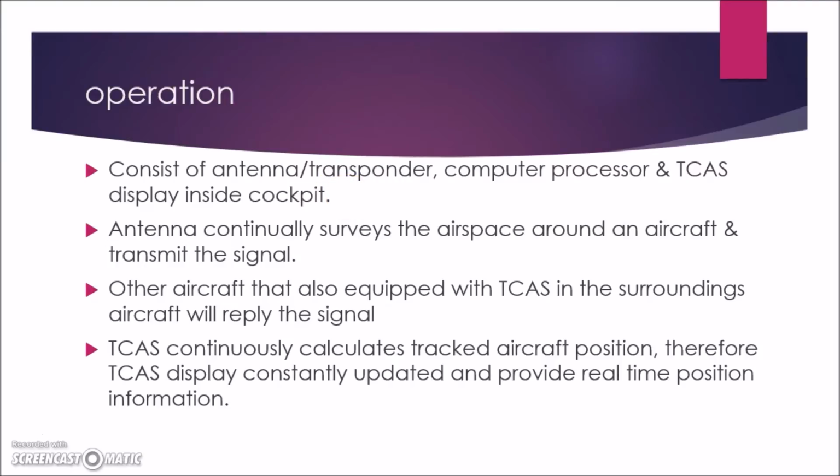Position can only be determined approximately by using the directional antenna, so it is only used for showing the other aircraft on the navigation display, but not for determining the resolution. The system activates if the closure rate is such that a collision could possibly happen in some specific time. That does not mean that the aircraft are actually on colliding courses. The TCAS system does not evaluate heading or positions. It is just that the momentary closure rate is high enough.